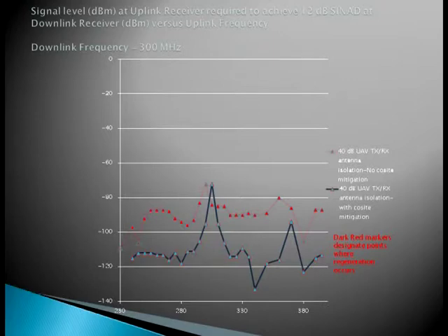When this occurs, the radio relay is locked up, and the radio relay power must be recycled to regain control of the relay. Obviously, this can be a significant problem with an airborne relay, as the relay is essentially non-functional when regeneration occurs.